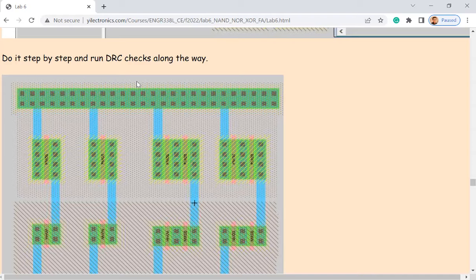And I think we haven't done that, but there are 3 types of checks. One is DRC, another one is called NCC, right? But NCC is a really odd name. It should be LVS. It's layout versus schematic. It's called LVS in any other tools, right? Keep in mind it's LVS. And there's another one, I think it's called well check or something.